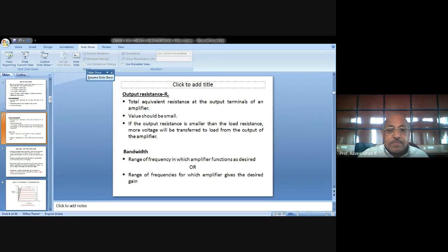So here this is the amplifier circuit. Here the very same R1 and R2 are made a voltage divider bias network. RC is there, RE is there, and these are all the coupling capacitors. Cin is the input coupling capacitor and CC is the output coupling capacitor. And this CE is the emitter bypass capacitor because it bypasses the emitter resistance RE connected in series with the emitter of the transistor. So there are three capacitors used in the transistor amplifier in the CE configuration.